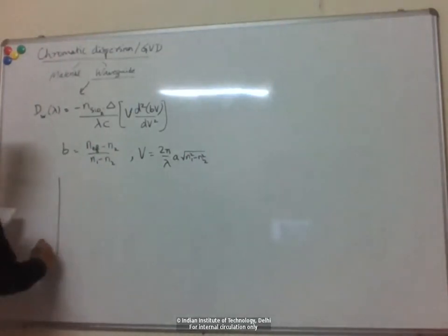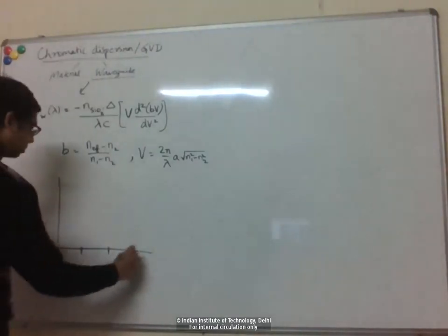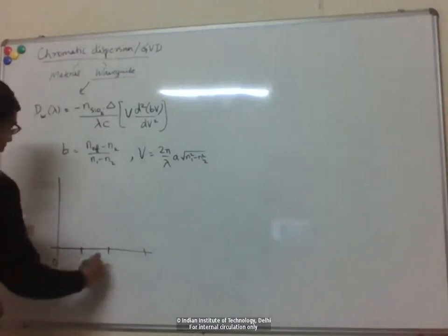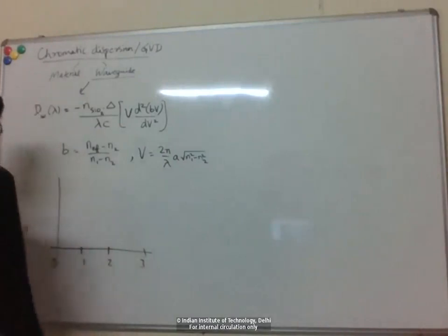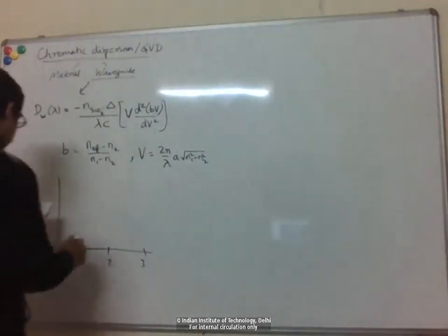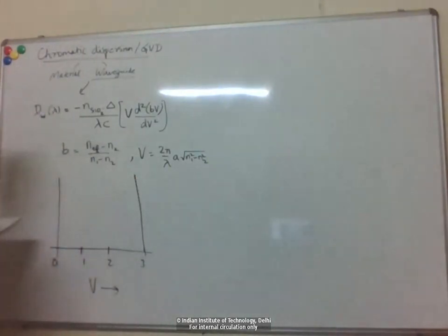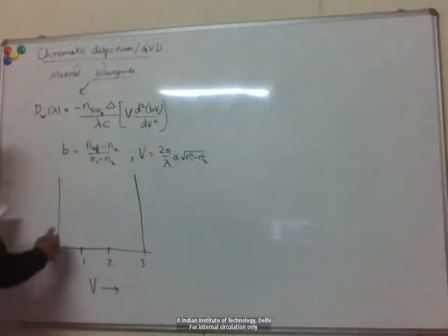Right, so if you look at a step index fiber, we get these universal bV curves, right, for different modes. And again, since we are only interested in single mode fibers because they are the ones in use for telecommunication systems nowadays, we are looking just at the lowest order, also called LP01 mode. Right, so if we plot this normalized frequency on the x-axis, then let's put some numbers on the y-axis here.